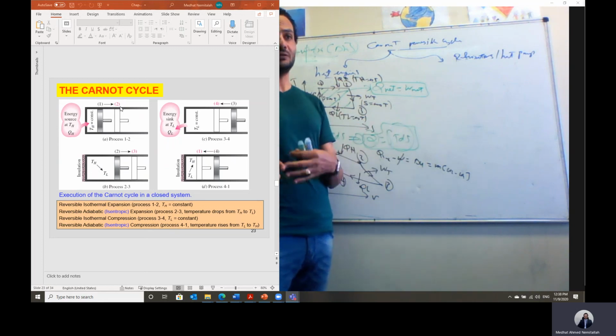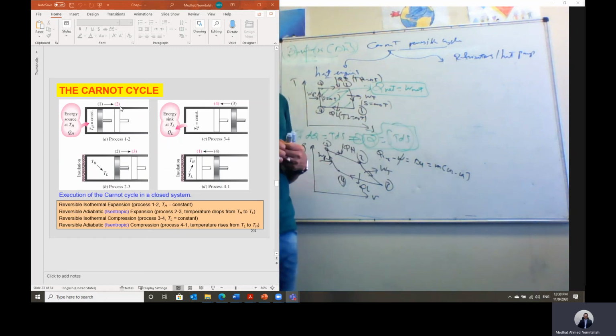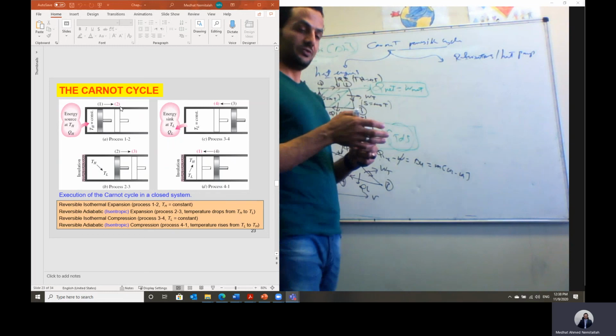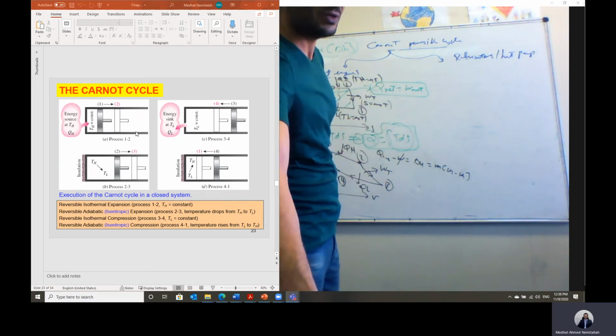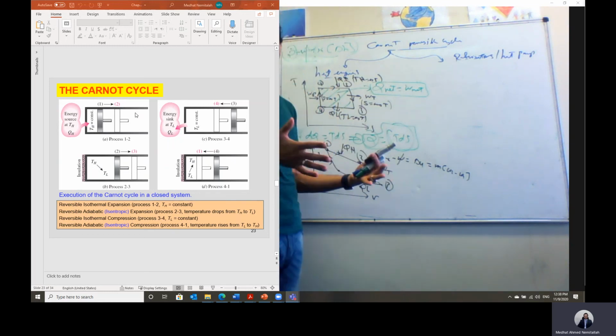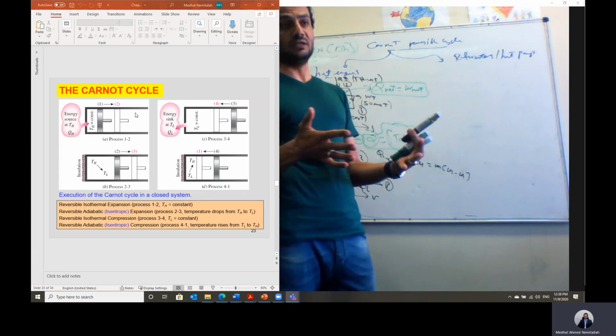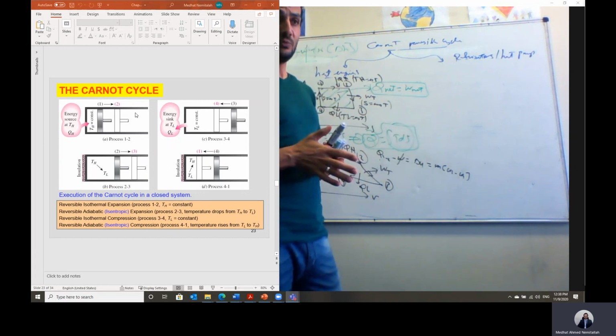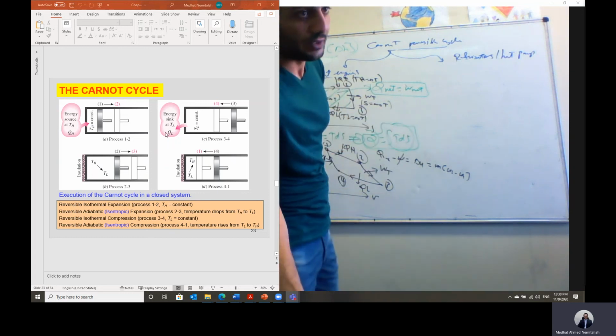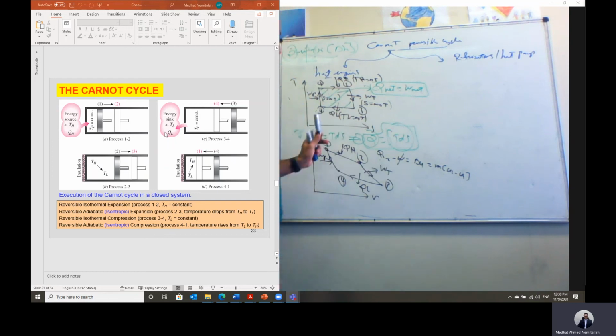we have boiler, turbine, condenser, all of these open system devices. Or it can be applied for a closed system cycle, like when we have an internal combustion engine. We have a piston cylinder device, and we burn the fuel and the gas. Then we can have an expansion process. This is typically the engine in your car. So in this case, the process of heat addition, we consider it a closed system.